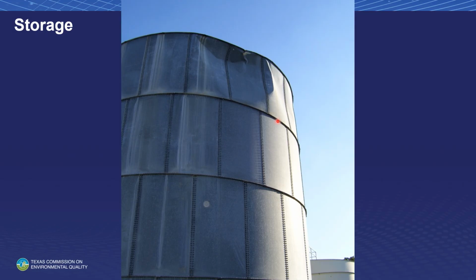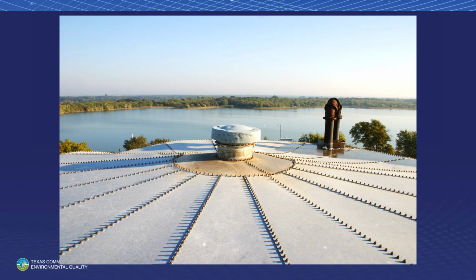This is a storage tank. Here's the vent on top of that storage tank. Don says he thinks an extra service pump turned on, and he couldn't get enough air in through this screen, and so it created a vacuum in the tank. My experience with these tanks is I've seen 3 of these collapsed tanks. In the winter, all 3 of them that I saw had gooseneck vents.